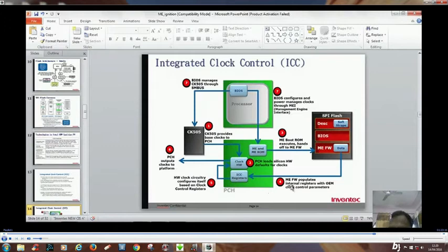So what is the fourth step? Fourth step is data which is present inside the AMI firmware goes to the ICC register. ICC register loads this into the clock hardware. It generates clock output. And what is the seventh? BIOS now manages CK505 through SM bus, and the BIOS will configure and manage clock through the management engine interface.